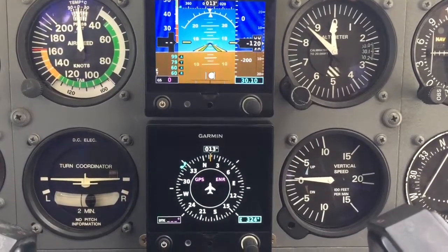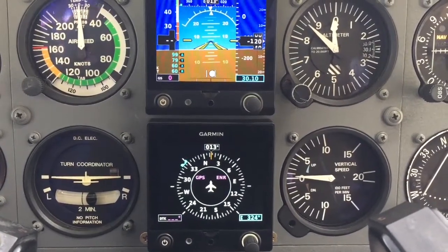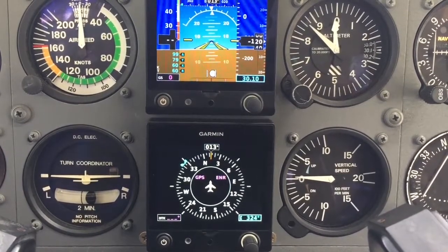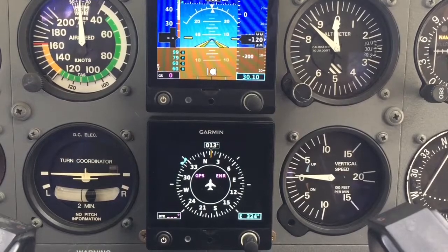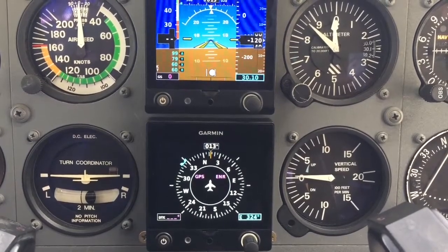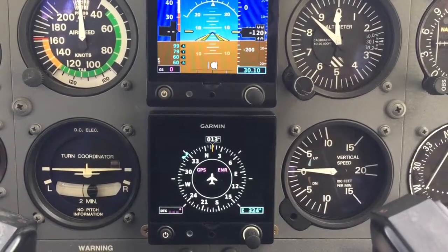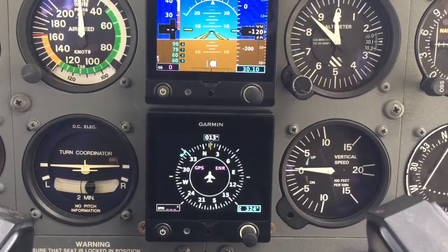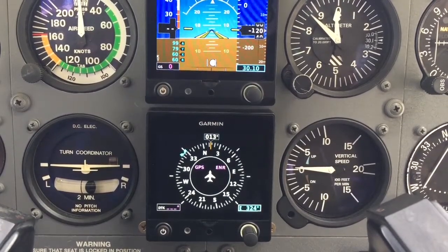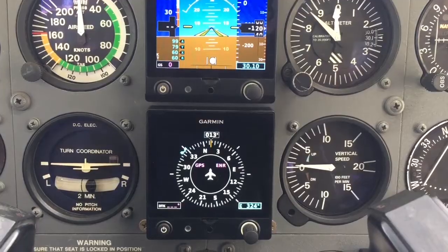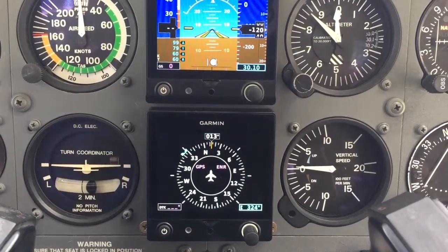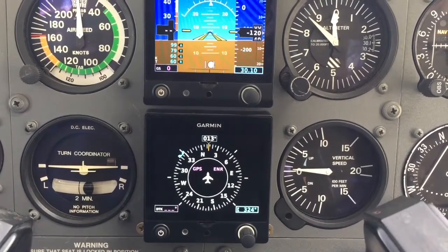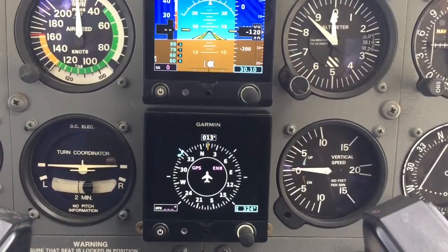The G5 HSI works like the directional gyro that you are used to and has an adjustable heading bug. Superimposed atop the card is a CDI needle, which can relay ground or satellite-based navigational course information. When used with VOR and GPS navigation, the G5 HSI provides course deviation, ground track, ground speed, distance measurement, heading selection, and instrument approach related information.